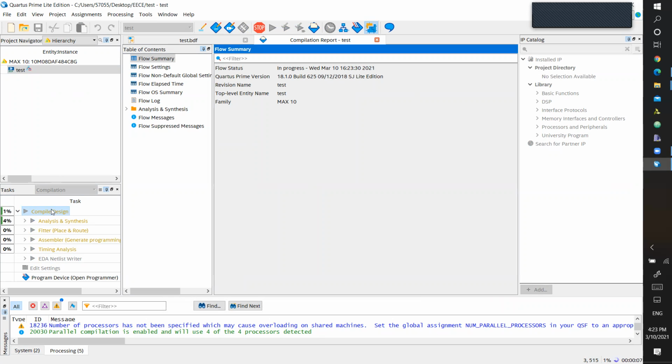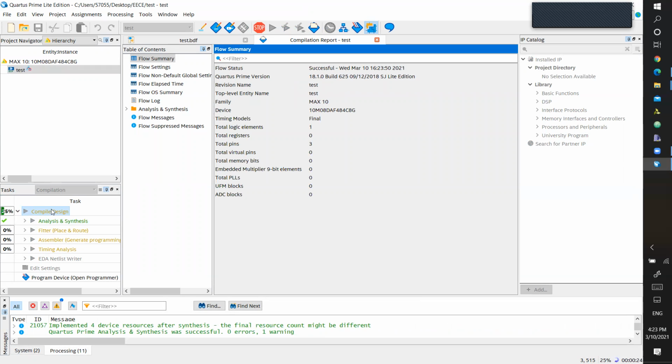This time I will type board. Make sure you use the printer cable, not the USB serial cable, to connect the board to your computer. Because now we need the printer cable, also called the JTAG cable, and this is what we need.